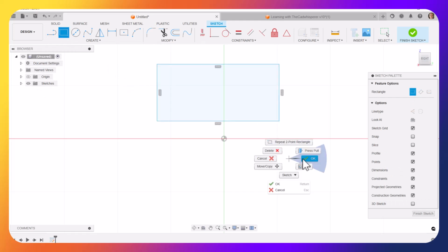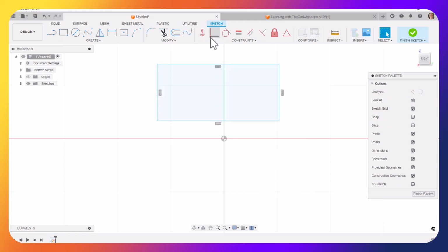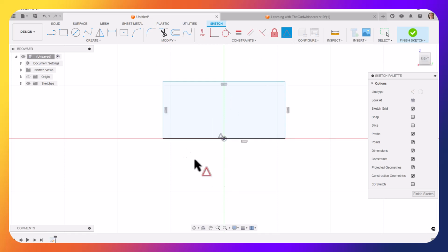And then I'm going to put a coincident constraint between the midpoint of this line, and actually let's do that as a midpoint constraint between this line and the origin. We see that it moves that line to the origin and that line changes black. I'm going to go ahead and dimension this line, and let's say that I'm going to make this 500 millimeters.